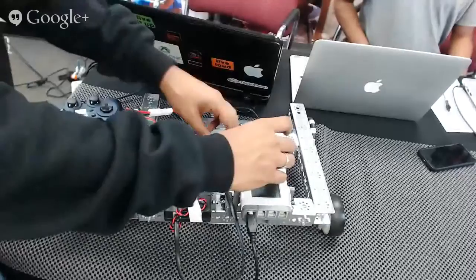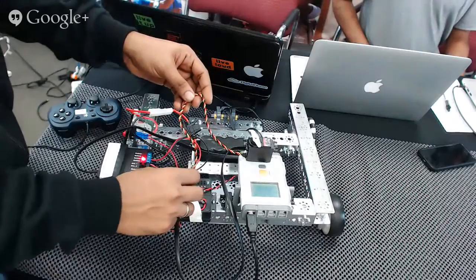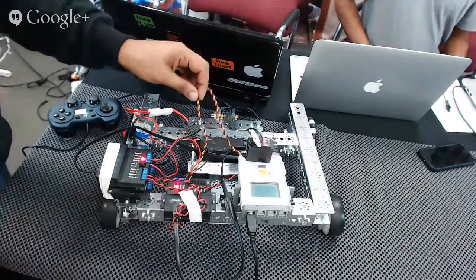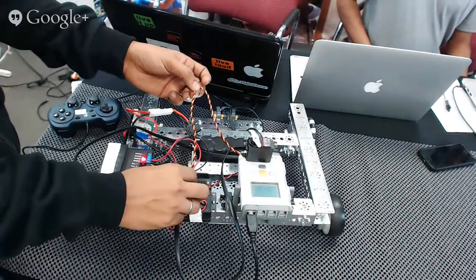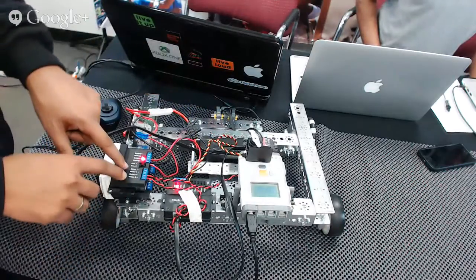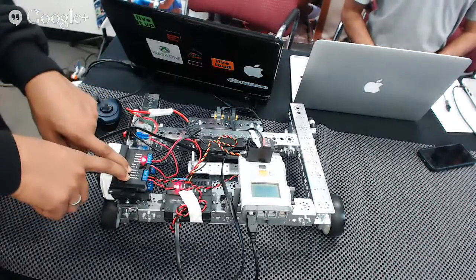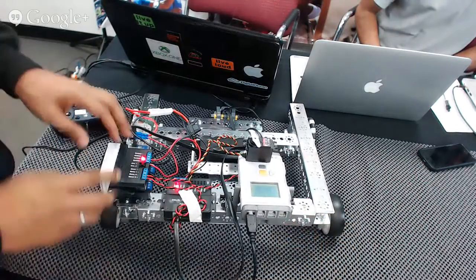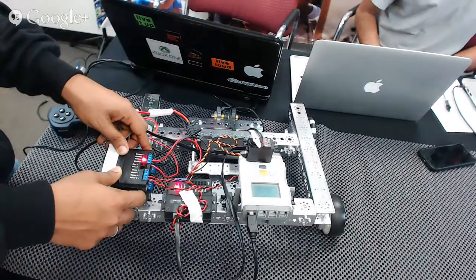We can see that we have the servo motor connected to the servo controller. This is a very simple connection where we connect it to channel 1. We have channels 1 to 6, so we can connect up to 6 servo motors on a servo controller. The first channel is connected to this servo motor over here. And we have two possible motor connections to our external DC motor controller, so we have the two wheels and their motors connected to it.